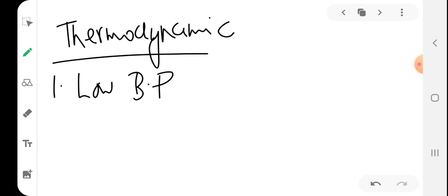So the liquid at the evaporator coil should vaporize easily. Easily means it should have a low boiling point. Otherwise, the compressor will have to create too much vacuum to cause the liquid to evaporate. So that is why it should have a low boiling point.